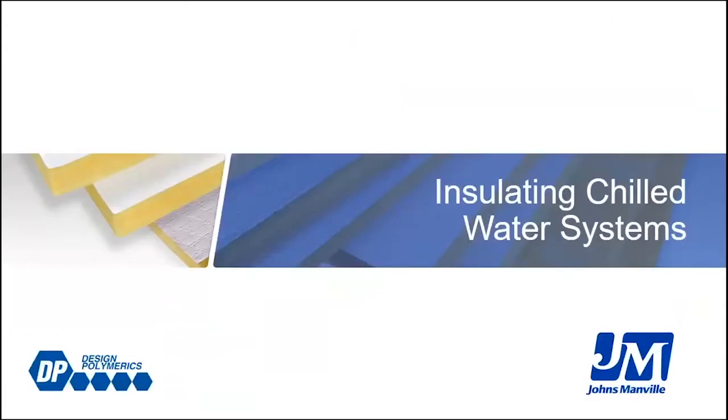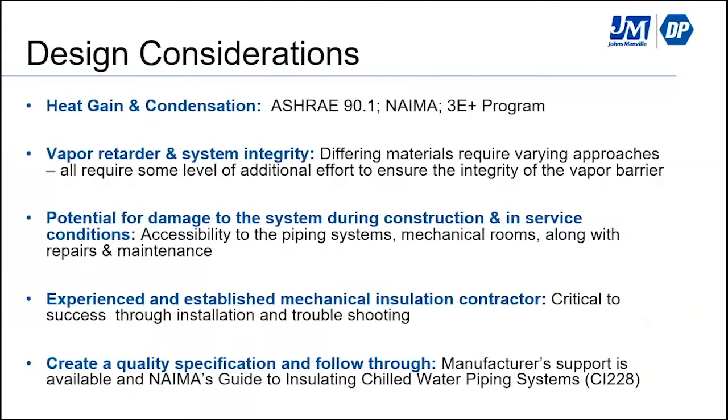So let's spend a little time talking about chilled water systems in particular. With chilled water systems, there needs to be a number of considerations taken in when you are designing those types of systems. One of the most important things is to make sure that you're preventing condensation, and we'll spend some time talking about that. But there's a program listed, the NAIMA 3E Plus program, and a reference from ASHRAE 90.1 that can help in determining how you would go about preventing condensation.